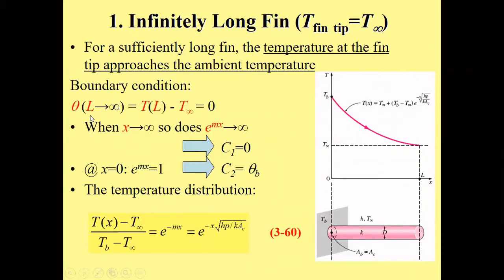You can write the condition at the fin tip like this, at x equal to L. Tip means at the very end of the fin. The difference between this and the ambient temperature is 0 because it's already the same.